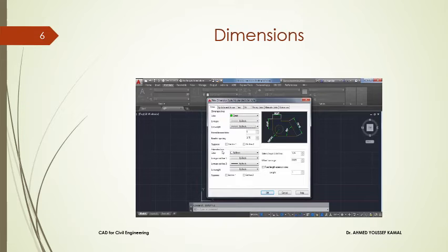Now for extension lines, which are these lines, you can modify options from this panel. So here also we have a drop down for color, extension type line 1, and for line 2 drawing line type. We also have a line weight option. Now when you suppress any extension line, that extension line will not be visible, but this you can also suppress from property panel, so you may ignore this part.